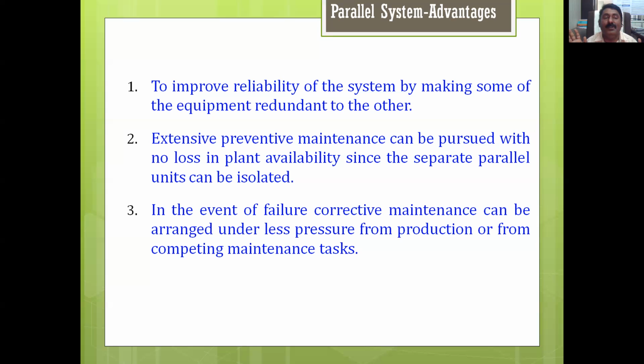One instrument stops, the complete line stops. No machine is working, and there is complete stoppage of the system. Therefore, there is huge pressure that whatever breakdown or corrective maintenance there is should be carried out immediately. But in a parallel system, there is not that much pressure. Let the corrective or preventive maintenance take its time, as the other parallel systems are running. So these are some of the advantages of the parallel system.